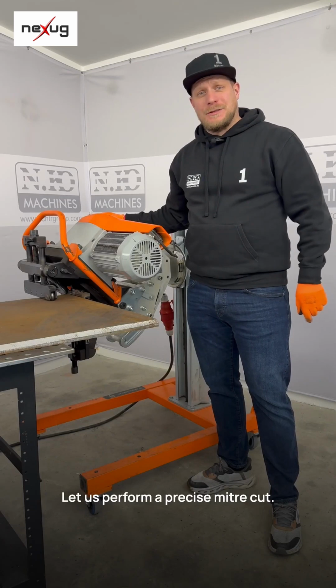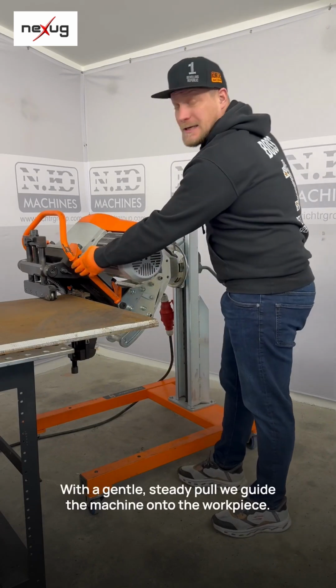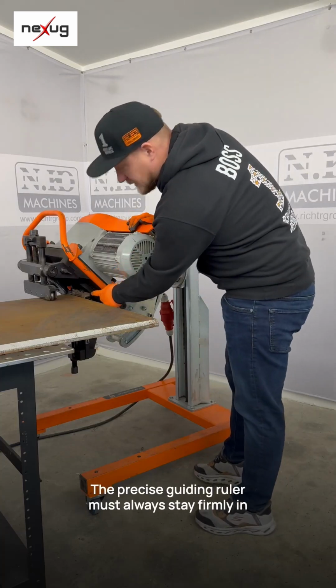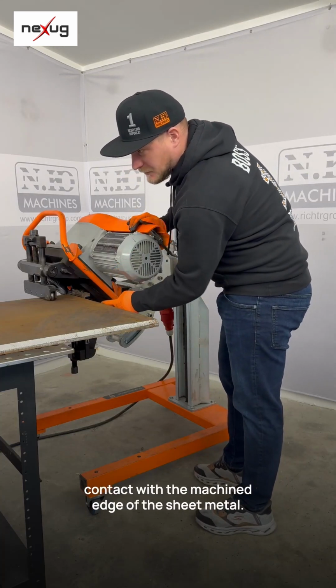Let us perform a precise miter cut. With a gentle, steady pull, we guide the machine onto the workpiece. Attention! The precise guiding ruler must always stay firmly in contact with the machined edge of the sheet metal.